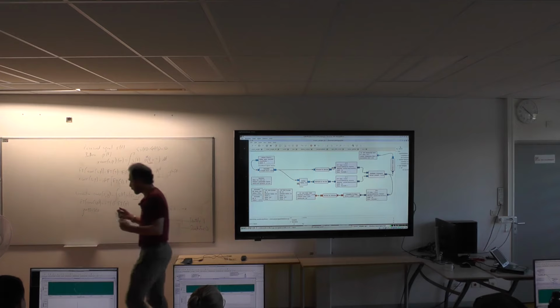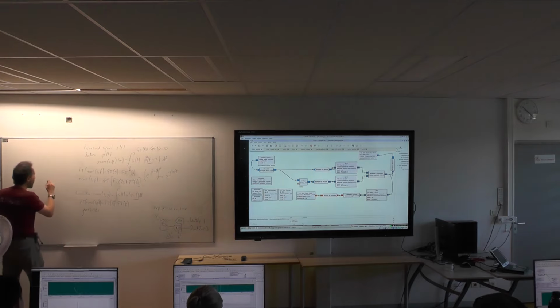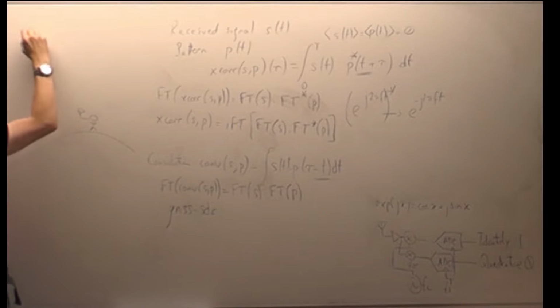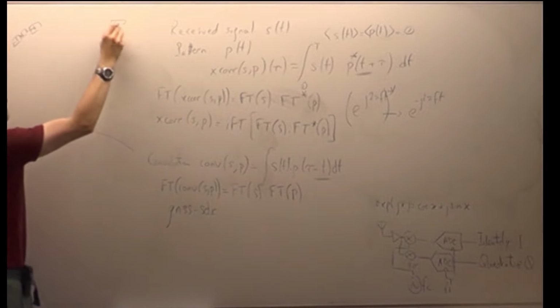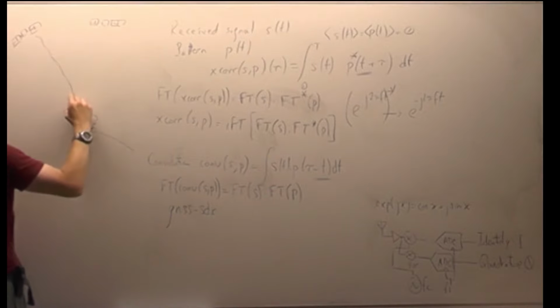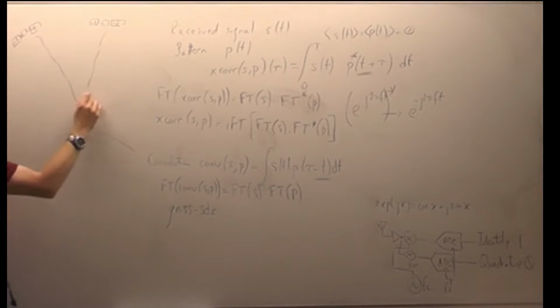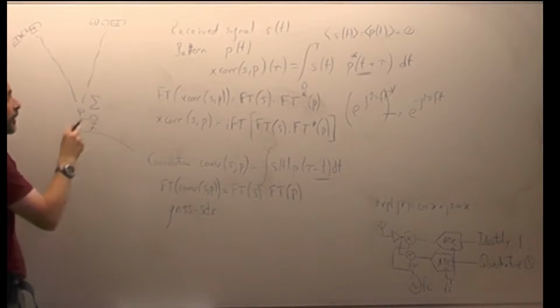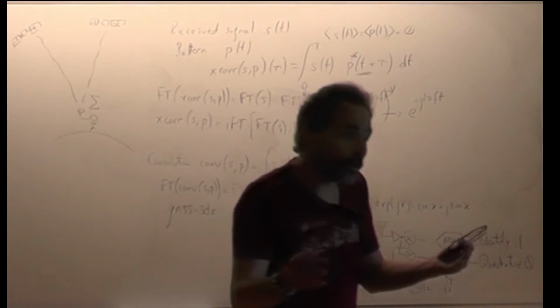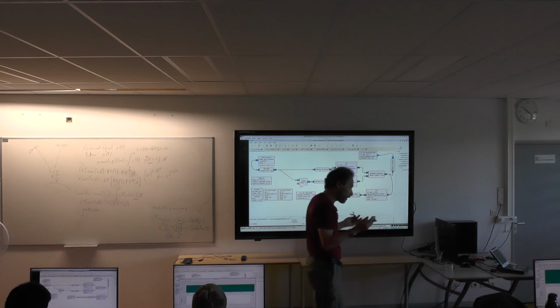But in real life, what are we going to get? In real life, we are, with our receiver, getting the information from all the satellites flying overhead, and all the satellites will be broadcasting at the same frequency. So what we get on the receiver is the sum of the voltages of all these satellites. And we want to decode each satellite individually.